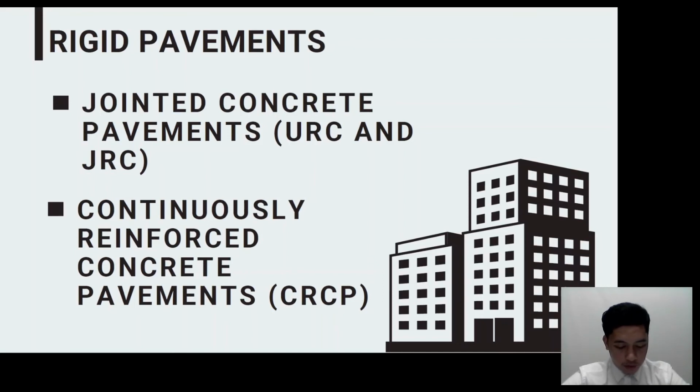The Transport Research Laboratory publication RR87, known as Matthews and Harding 1987, is like LR1132, empirically based, taking account of full-scale concrete road experiments.